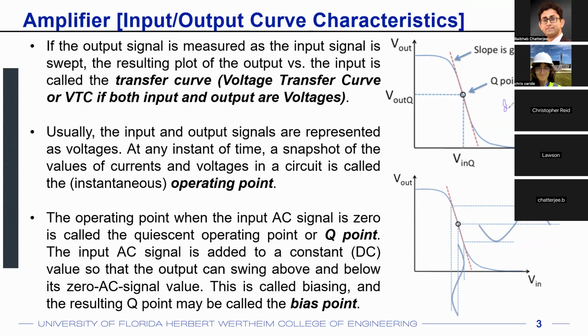So your dV out, that is the small variations or small fluctuations at the output, divided by dV in, that's going to be your gain, right? In terms of AC, in terms of small AC signals. And we'll discuss more about small signals in today's lecture. So if this is your gain, a small fluctuation in your output voltage divided by a small fluctuation in your input voltage, you also note that this is basically the derivative of your output with respect to your input, which is also the slope of this VTC. dV out over dV in, that's the slope of this VTC, correct?